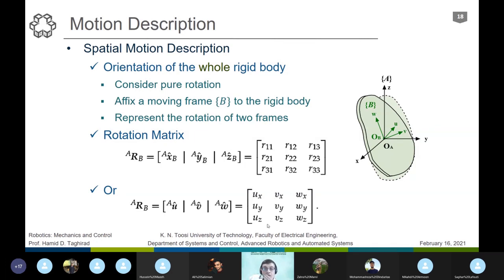So this is somehow the most general representation, but it needs 9 components. We know that if we have a general rotation in space, we have only 3 components, 3 angles. Why do we have 9 components here? It is just easier to manipulate, but much harder in terms of representation. And we will show that although there are 9 components here, only 3 of them are independent. So there are some other aspects to it.